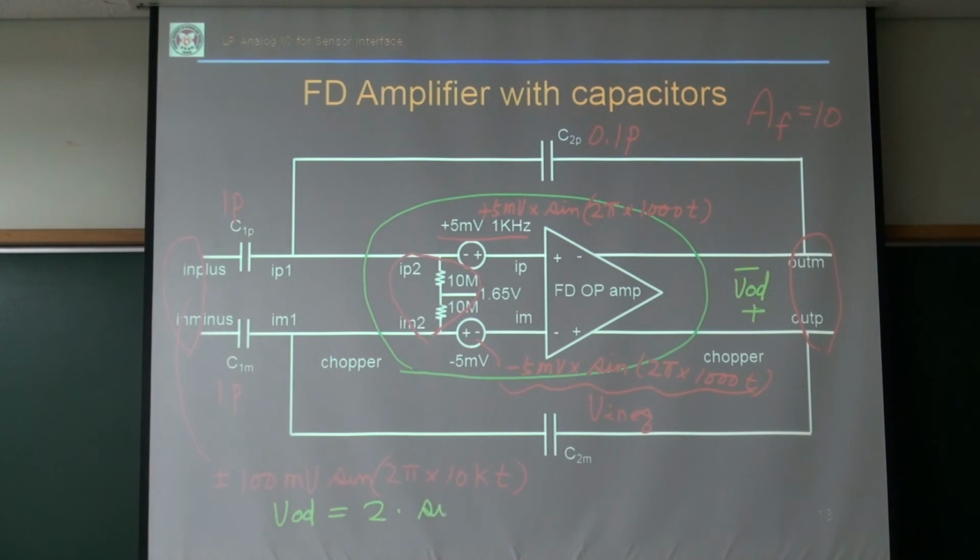Sine 2 pi 10k t plus, yeah, this 5 millivolt noise, actually differential 10 millivolt noise, right? The 10 millivolt noise will be amplified by the voltage gain.